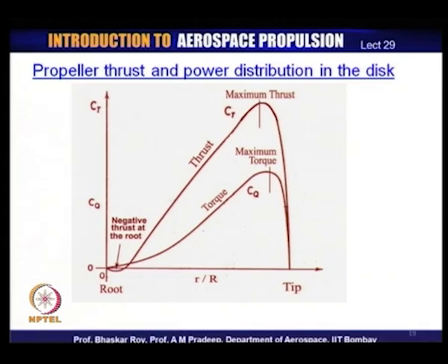So, this is what the propeller theory is. The first propeller theory is a very simple theory that quickly tells us what the thrust is likely to be, even during the takeoff operation of an aircraft, and it gives us a very good estimation of the efficiency over the advance ratio variation, with a slight increase in the values of efficiency.